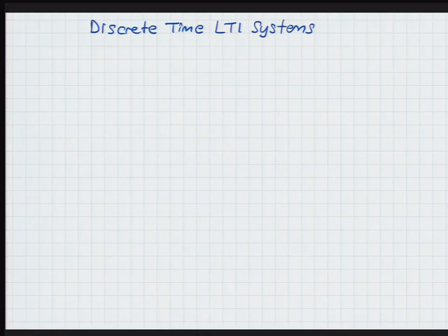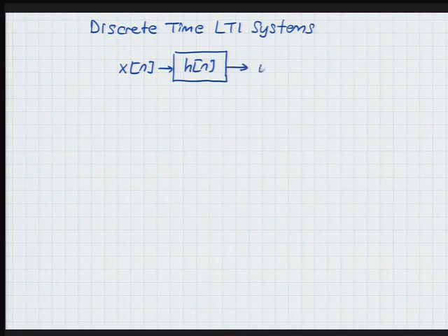So today we'll build on the Z transforms that we started discussing last time, and we'll start analyzing linear time invariant systems in discrete time with Z transform methods. The key feature of LTI systems is that for them the convolution property works, meaning that if you know the impulse response to your system, h of n, then whatever input may come in, the output is given by a convolution operation of the input and the impulse response, right? Now, what does this mean if we take Z transforms?